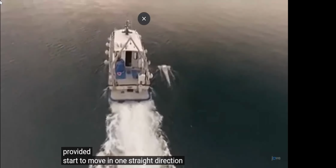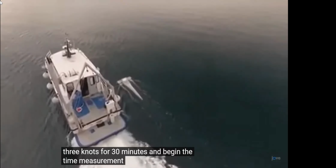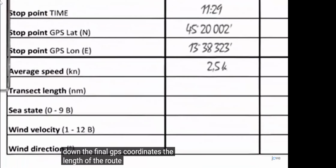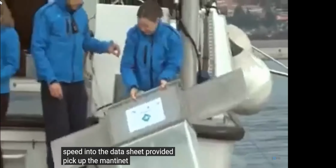Start to move in one straight direction with a speed of approximately 2 to 3 knots for 30 minutes and begin the time measurement. After 30 minutes, stop the boat and write down the final GPS coordinates, the length of the route, and the average boat speed into the datasheet provided. Pick up the MantaNet from the water.